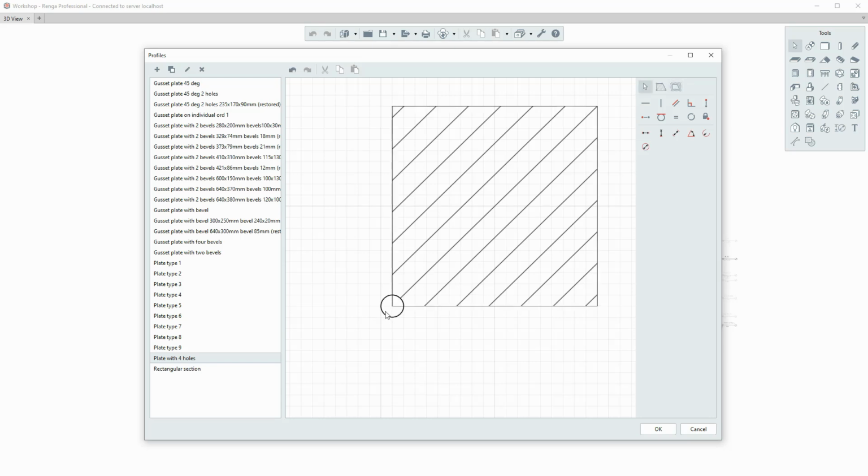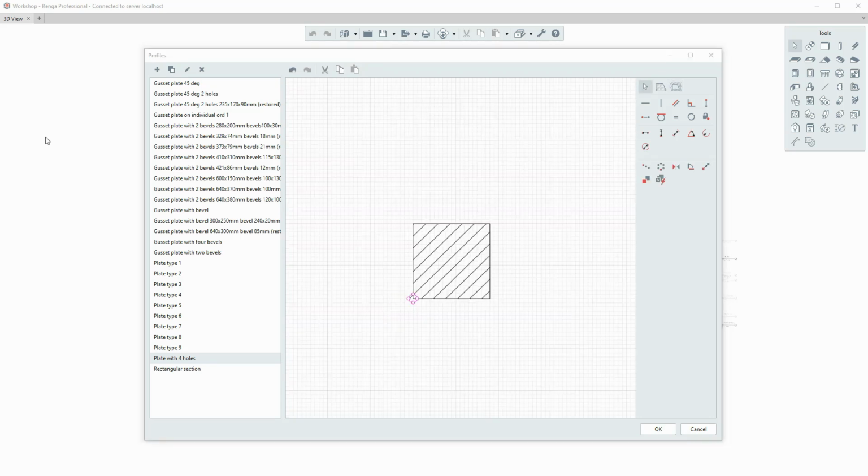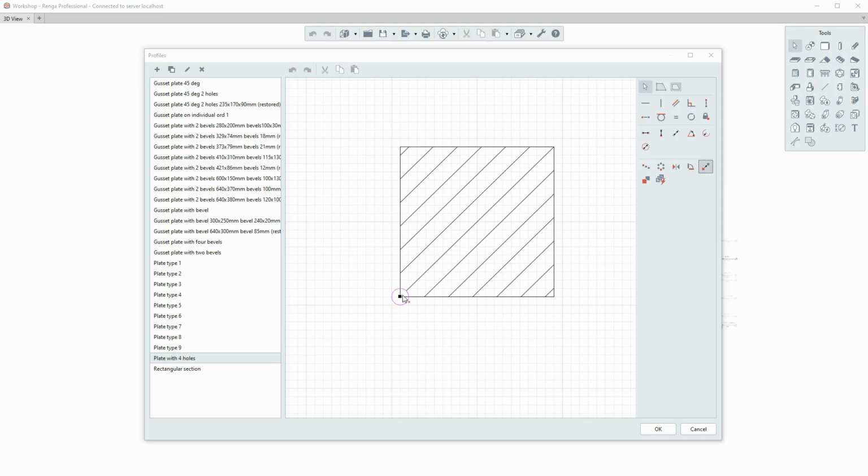The following actions are available with each selected outline: direct array, circular array, mirror, rotate, move, create copy, and apply constraints automatically. When applying an action to the selected outline, the parametric constraints are created automatically based on its shape. Apply constraints only for those cases when the created profile will serve as a prototype for creating new styles of beams, columns, plates or holes. That is, when changing profile parameters, only its dimensions should change, but the appearance remains unchanged.